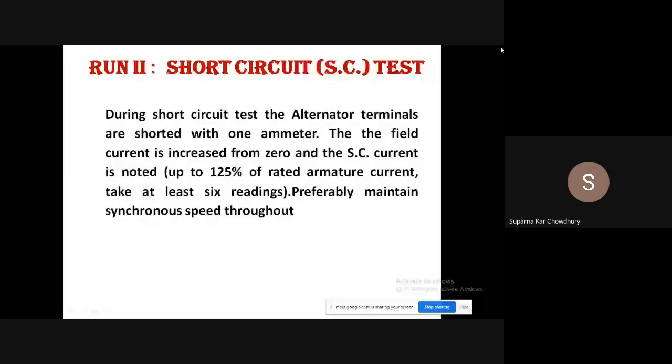Similarly, the reactance of the machine is proportional to the frequency. So approximately the short circuit current, which is the voltage divided by the impedance, neglecting the resistance, is basically voltage divided by reactance. So that is not affected by the speed, provided that the resistance is negligible.